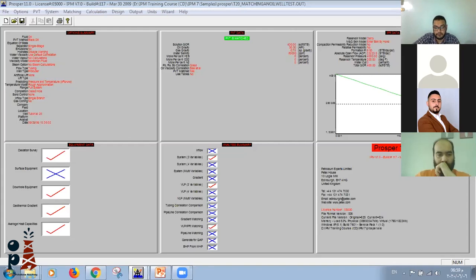Because mostly flow regime is about the slippage or the difference in superficial velocity, which I'm going to speak about here. Normally, when we have a water cut of 50% at the surface, okay, we imagine down there at the wellbore it will also be 50% oil and 50% water.